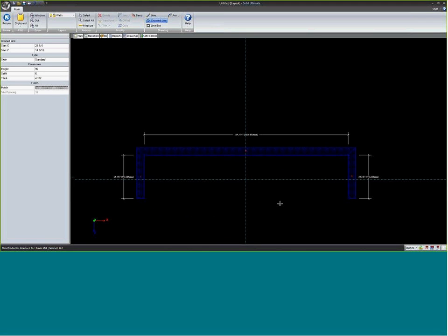Now, there are several different types of walls. What we've been doing up to this point is just a standard wall. If I click on my line tool over here, I've got style. I can pick standard or peninsula, cathedral, vaulted left, or vaulted right. The cathedral, vaulted left, and vaulted right are pretty self-explanatory. I don't use them terribly often, but a lot of designers like to show the way that the ceiling's vaulted. You can control how high it is at the peak or where the peak is located, if it's vaulted left and right, those kinds of things. So we won't really cover that today, but you can play around with it and see. It's pretty intuitive stuff.